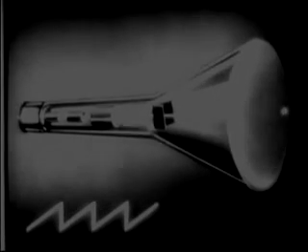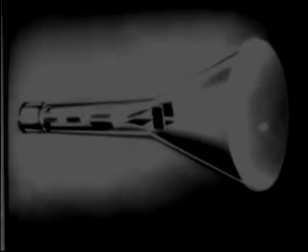But when sawtooth voltage is applied, it causes the beam to sweep across and snap back quickly. At normal speed, we get this picture, or an apparent baseline. The pips are formed by the action of the vertical deflecting plates, which bend the beam up and down each time a signal pulse is received. Thus, you can see that the electron beam is affected by both the horizontal and vertical deflecting plates.